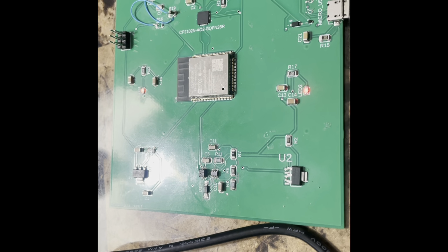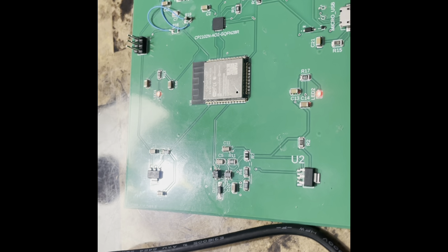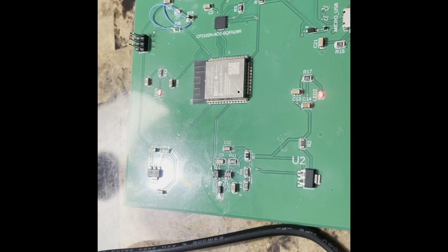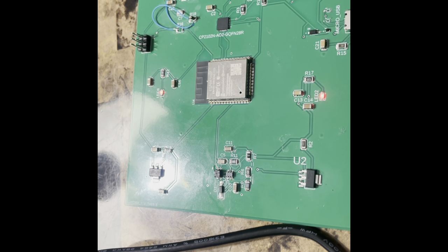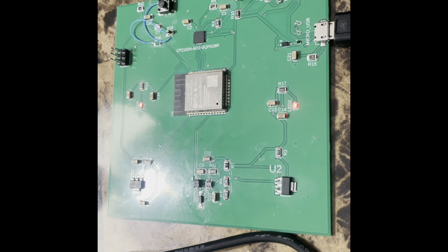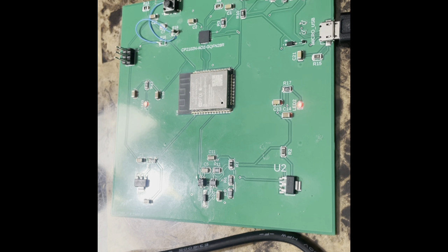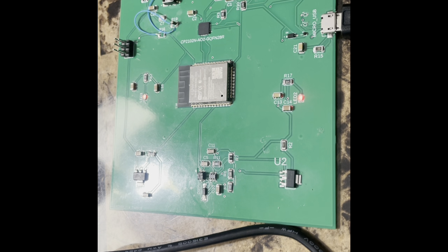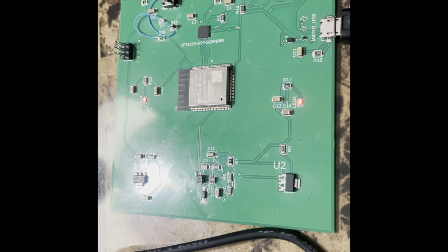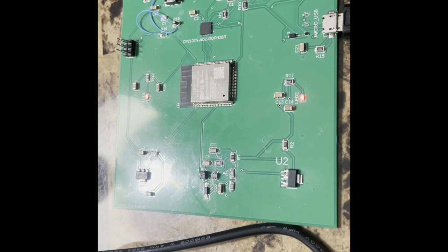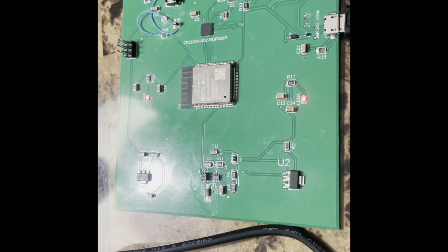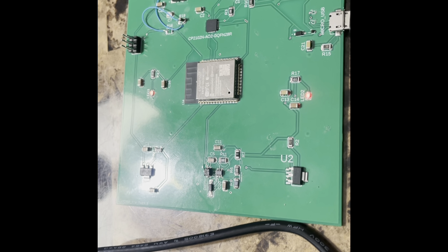Not a known issue was the boost switching regulator that we used. That one was not working. One of the main known reasons why it wasn't working was due to the MOSFET that we used was implemented incorrectly, in addition to the actual regulator itself having issues when adding load to do testing.